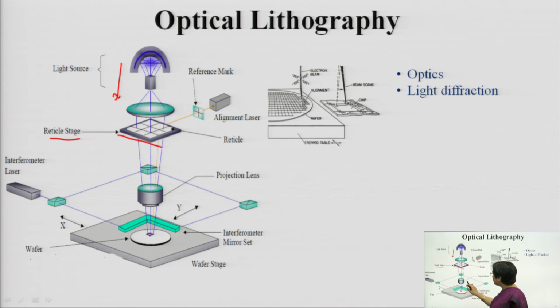So, you have a projection system or projection lens. The reticle is used for the mask alignment, and for this you have the reference mask. Through this reference mask, exactly line by line the mask will be aligned, and that will be imprinted. Here you also have wafer alignment; the wafer is always indented, and accordingly the wafer will be placed onto the chuck. You have a wafer stage over here, the wafer will be placed precisely, and the beam will be moved,